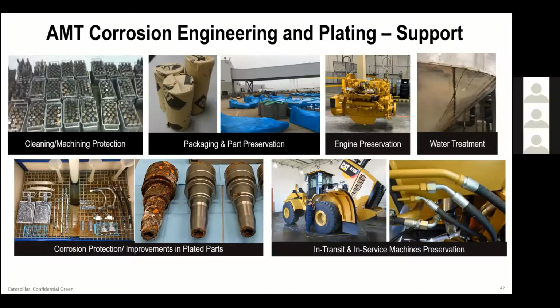Over on the right-hand side, I mentioned this a little earlier. This is quite interesting, because you think of stainless steel and you don't think it's going to corrode, but there are different types of stainless steel and different alloys. This one here was 304, and 304 cannot handle high chloride concentration. So you make a very corrosive environment, like the erosion you see on sidewalks creating potholes. With high chlorides, and it doesn't take much, 400, 500 ppm, in water that's being recirculated in the system, it started this type of corrosion.